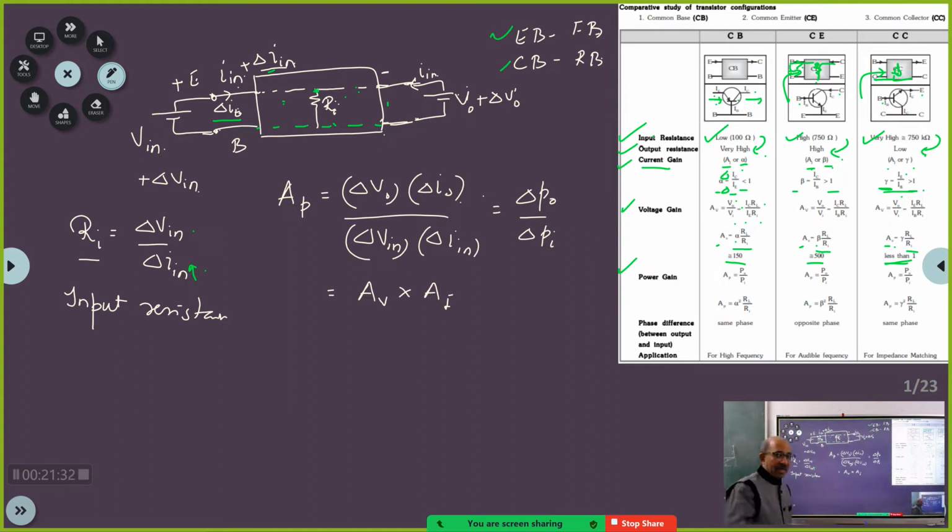So you see, you can enhance the power. In a transformer, even though there is step up voltage, you are not enhancing the power. The input power is equal to output power, provided there are no transformer losses. But in the case of an amplifier, the output power will be more than input power. Why? Because the amplifier will abstract the energy from the DC sources. You are giving biasing sources now. From that it will take the energy, mix that energy with the input energy and throw it at the output. That's why your energy at the output will be enhanced. Did you capture what I said?